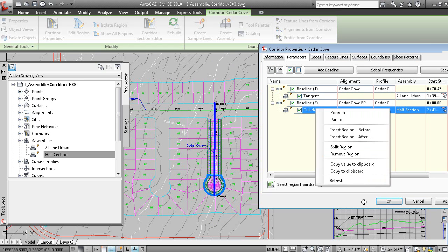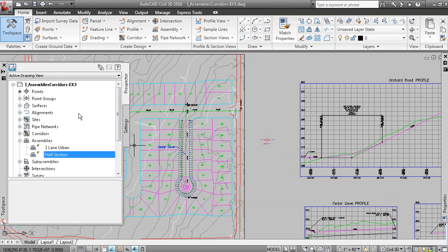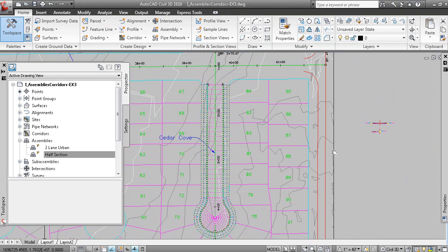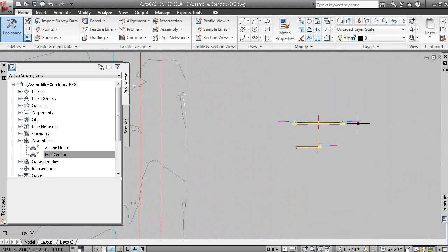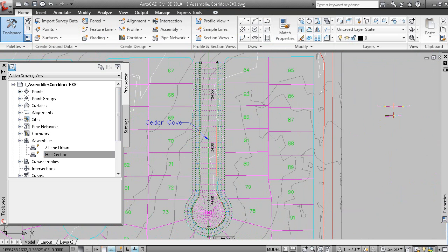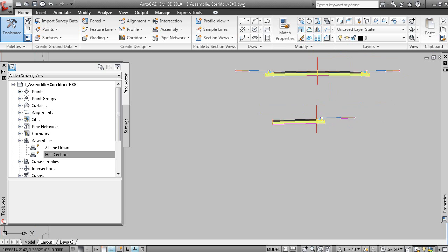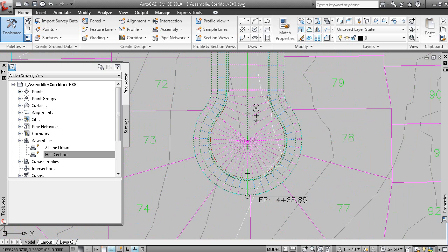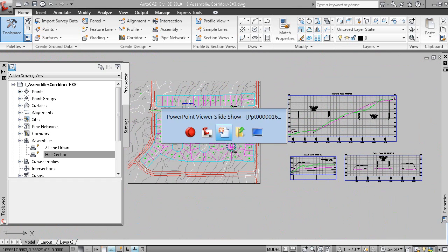So a little bit of a complicated example from a corridor creation perspective, but you know, we're not designing simple roads out there very much. We are designing these sorts of things. So essentially what we do is we take this typical cross section here, this is the full section, run that along the alignment profile for here up to this point here, and then we take this little half section and we run that around an alignment and profile developed for the edge of the pavement here. And that's essentially all this data that you see over here.